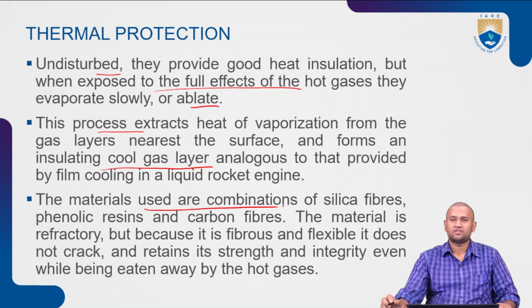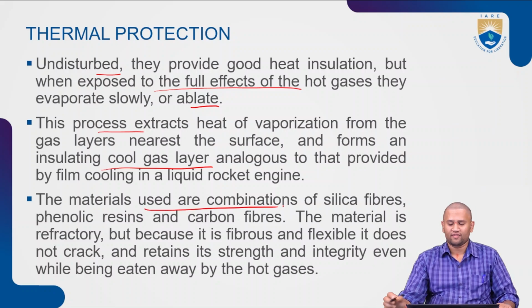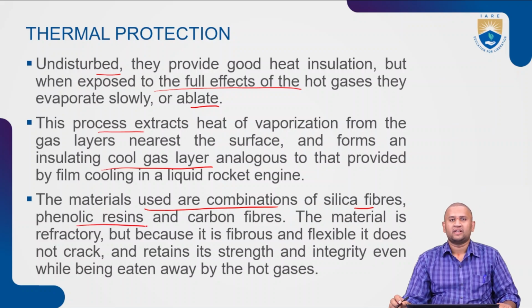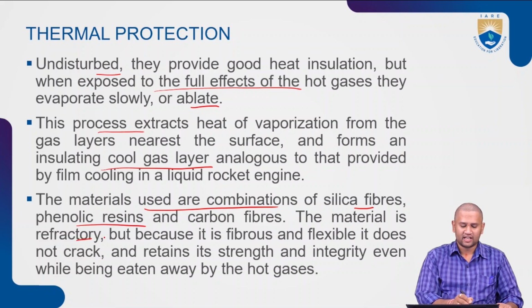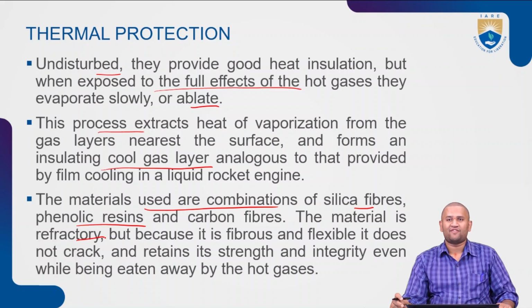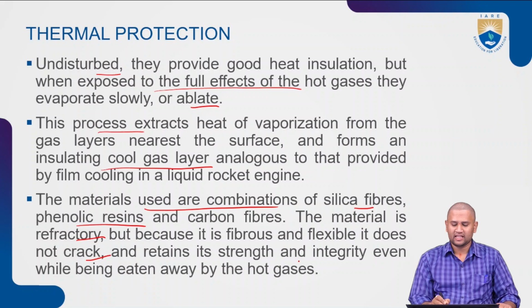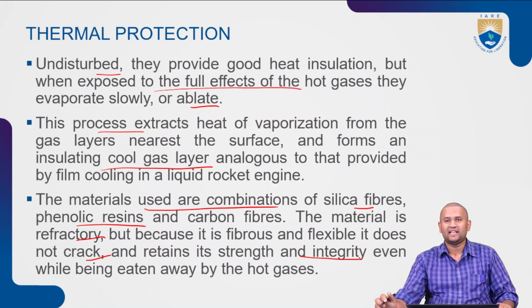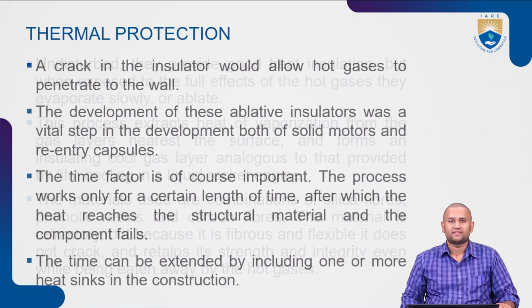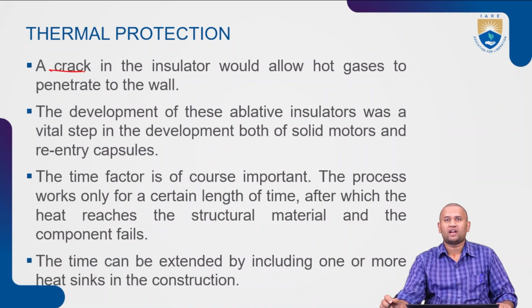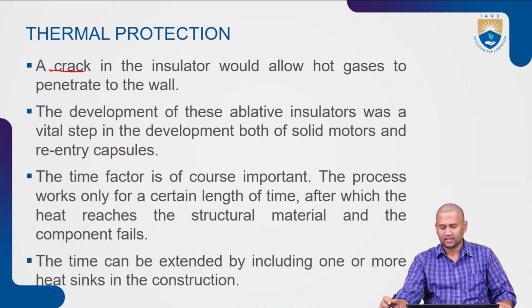The materials that are used are combinations of silica fibers, phenolic resins and carbon fibers. The material is refractory, but because it is highly fibrous and flexible, it does not crack and retains its strength and integrity even while being eaten away by the hot gases. A crack in an insulator would allow hot gases to penetrate the wall, right?